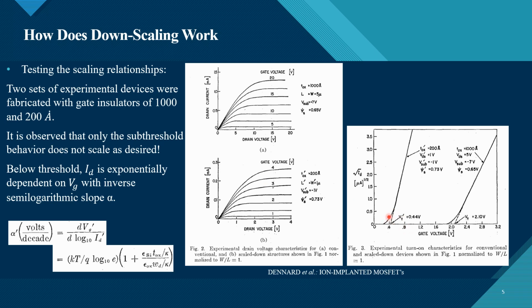Here, if we see the graphs below the threshold voltage, these two are identical, and therefore we conclude that only in subthreshold voltages we do not have the scaling as we wanted.